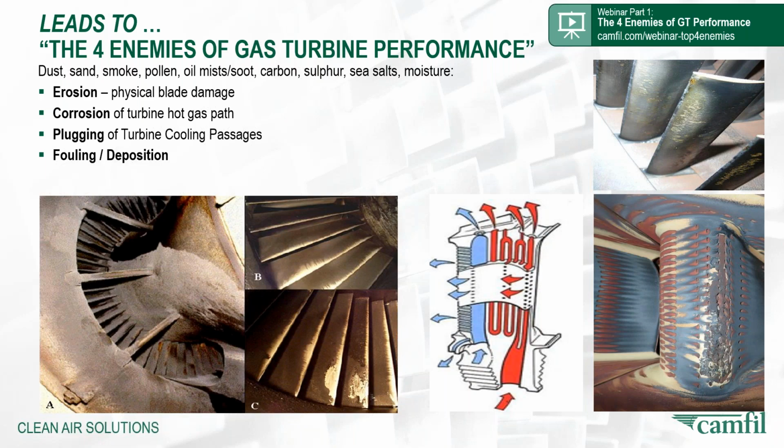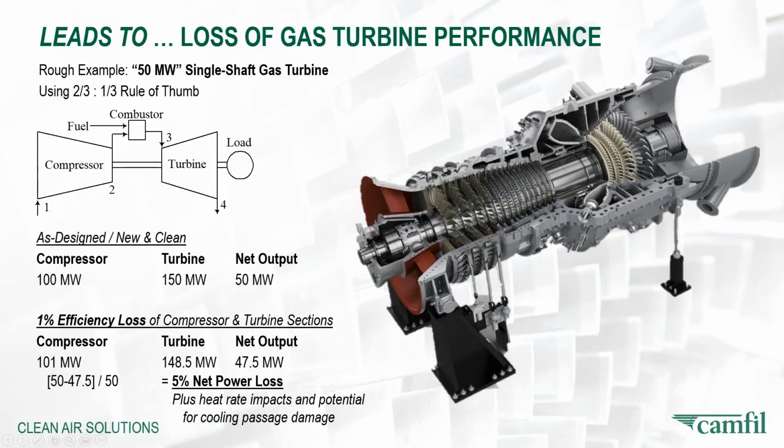In the middle picture, we see the intricate passages which are cast into rotating turbine blades and the stationary blades. If those plug up, the cooling of those blades is impacted. And fouling and deposition, and we see that in the lower pictures to the left, where we see physical dirt basically residing on the turbines, dramatically impacting the efficiency of the machine. Next slide. What does this lead to?